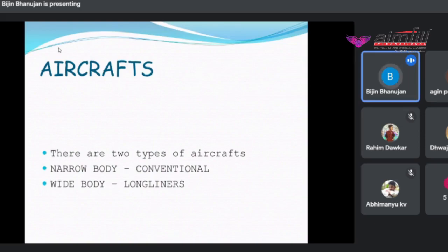You will have very little ground-to-air communication. The aircraft needs to maintain steady visual flight rules, and lots of other problems come up when the weather changes, because you're crossing the Pacific Ocean. There's a chance of storm, or a tornado, or lightning. So these problems will be huge, and if you don't have enough payload on the aircraft, or enough fuel for that sector, that's going to create a lot of trouble. You can't just come back with that amount of fuel. So you need to always plan very deeply how the sector goes when you're crossing an ocean, or there's a flyover sea.